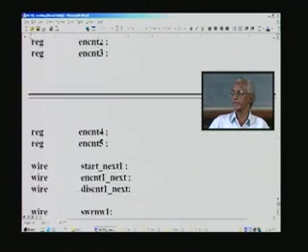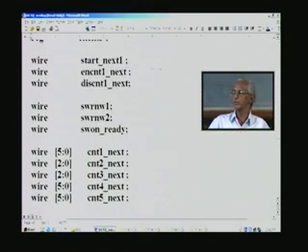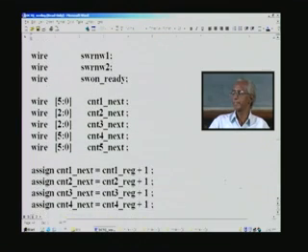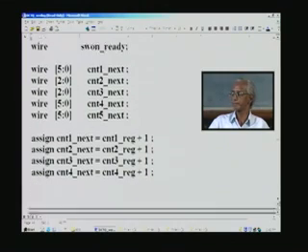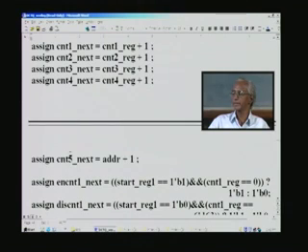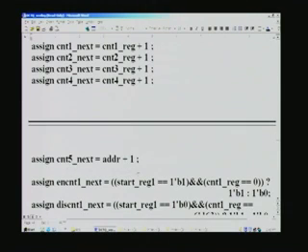So, we declare them as reg here, and we also need intermediate results which we will cover later on, and for that these are all the signals that we use, and we also need pre-incremented signals, which is basically using assign statements, and they are declared as wire here, and the actual counter 1 reg is this one, which is pre-incremented here, and that is what is done here, including the DCT-Q coefficient address.